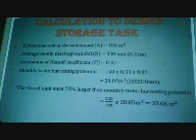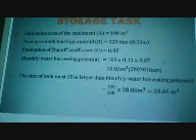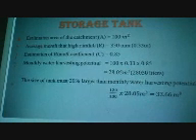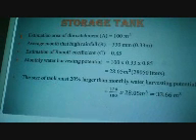First, the estimated catchment area of rainwater, we estimate 100 square meters. Average monthly rainfall height, 330 millimeters. Estimation of the runoff coefficient, that is rainwater running off the roof, is 0.85.